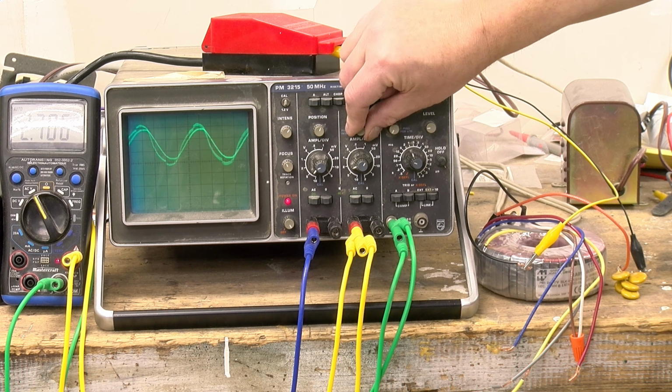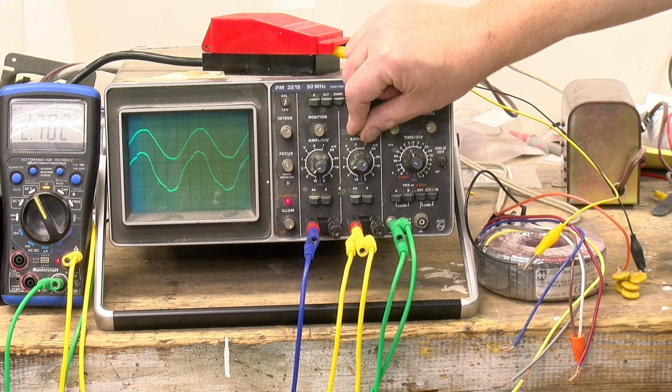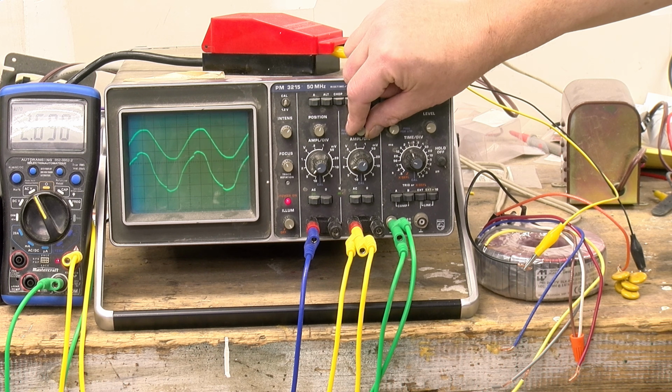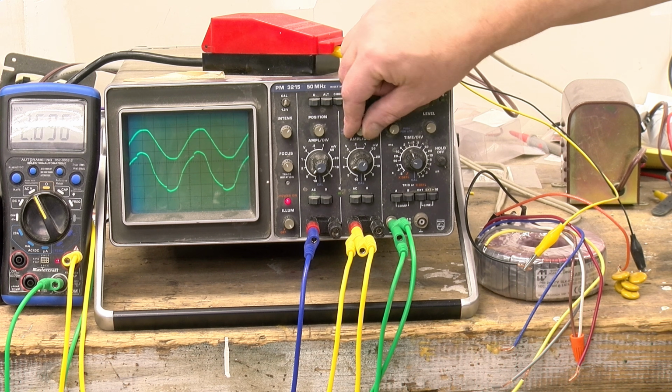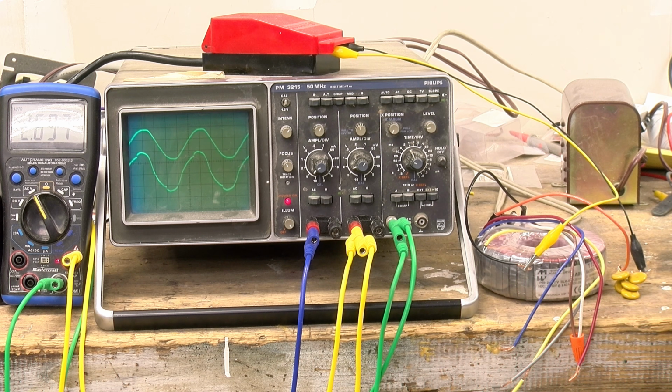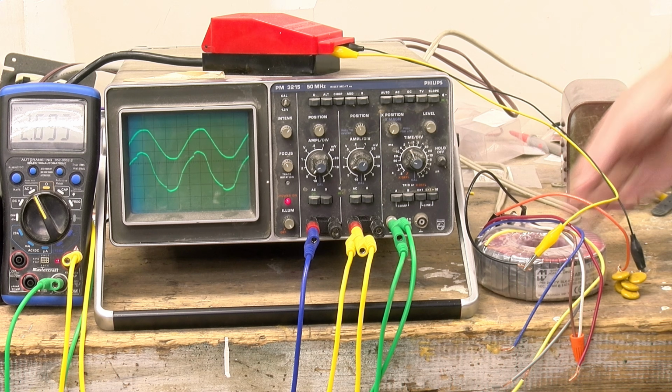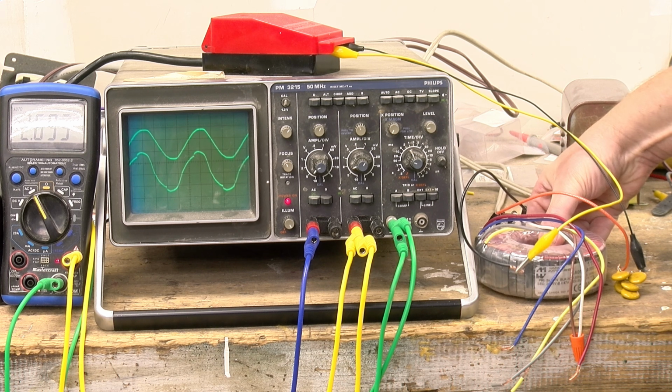This was as close as I could get, and it's very close. So this would actually be very close to a power factor of 1 because those waveforms line up so nicely. Whereas when we only had the capacitor, it was probably more like a power factor of 0 because it was pretty much at 90 degrees. And when we had just the inductor, it was probably a power factor of around a half or so. All right, so that is the stuff we looked at last time.